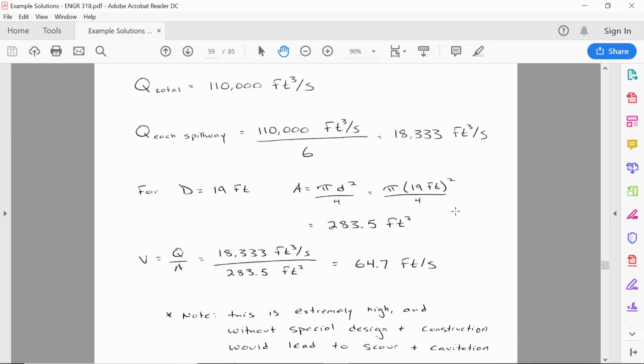And so the risk of cavitation is this pressure can go below atmospheric pressure. In terms of gauge, it can go negative. The pressure in the pipe can go negative. But when that pressure approaches the vapor pressure of the liquid, then cavitation is when the water is boiling, when it's going from the liquid phase into the vapor phase without any additional heat added to the water.